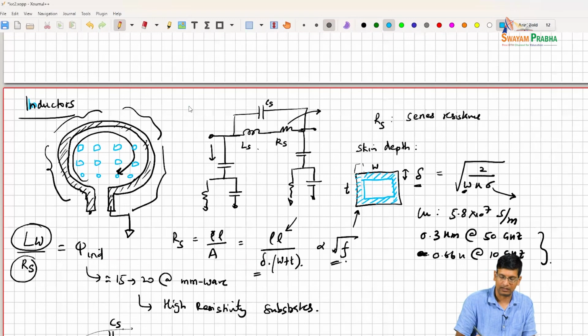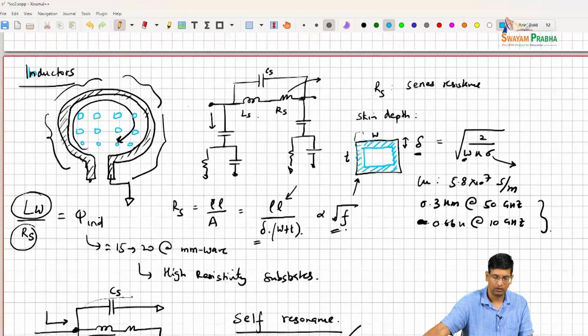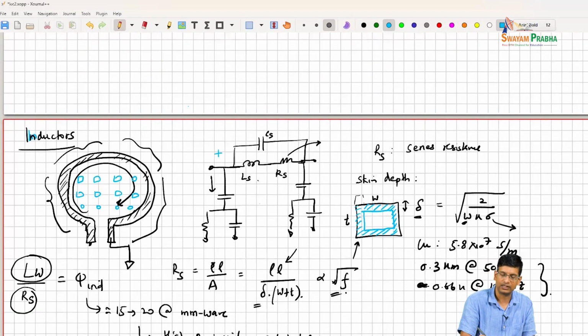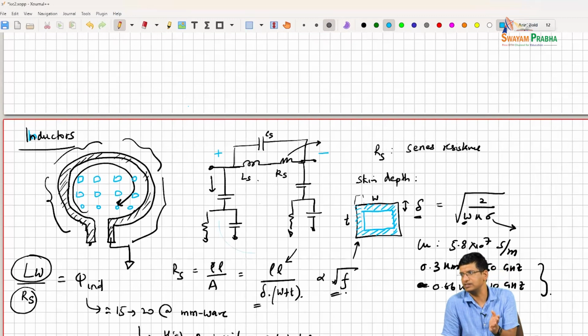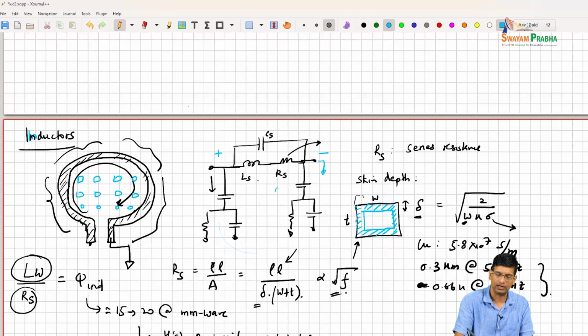And again, how we choose to use the inductor matters. So the same inductor, when we were using single-ended, looked a certain way. But if we are using a differential, for example, then what you would find is that these capacitances and resistances would show up in shunt, right? So you have to think about the inductor model that you are using, whether you're using it differentially or single-ended, to figure out which of those resistances matter for you, right? For example, if this port is grounded, then all of this side doesn't matter, right? So it's something to keep in mind.